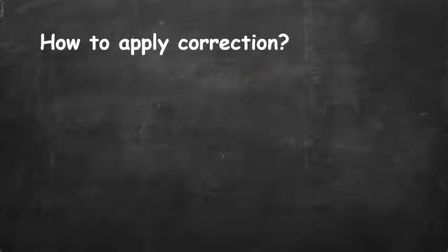So how are we going to apply correction based on the due to sag? So always remember na ang ating C sub S or yung correction due to sag is always subtracted. So from the measured or layout distance because it tends to make the measured length or distance or layout or measure this as longer than what it should have been. So we have here the formula.